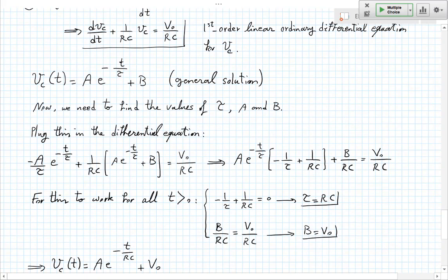When you have a first order circuit like this, described by a first order differential equation, and the answer following an exponential decay like this, that parameter, that factor that comes out in the denominator of t is called the time constant. And this is, by the way, a very, very generally useful and widely used concept in all science and engineering. Not just in electricity.